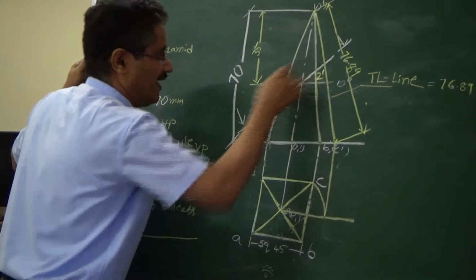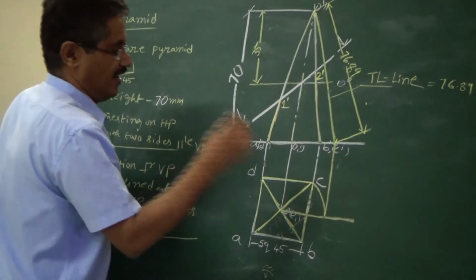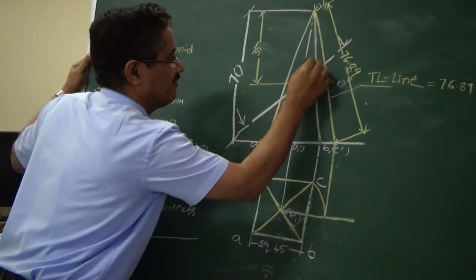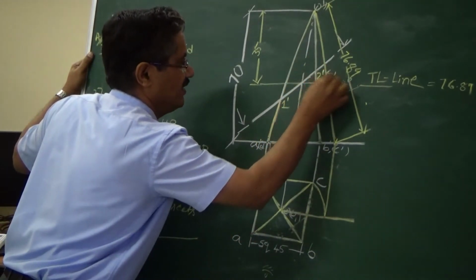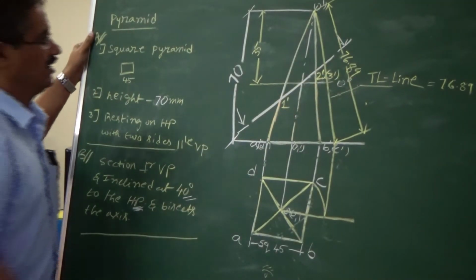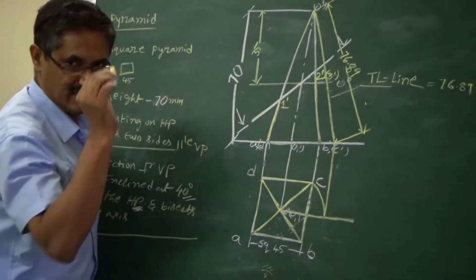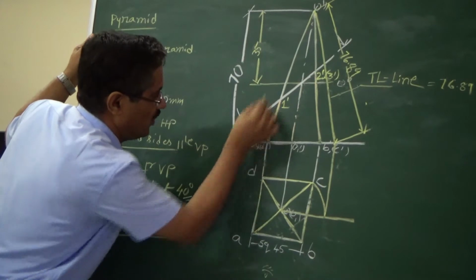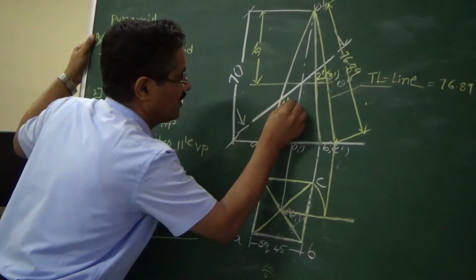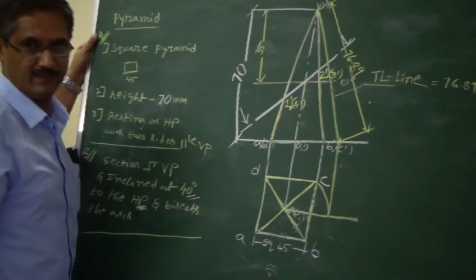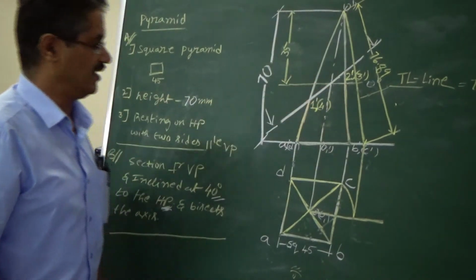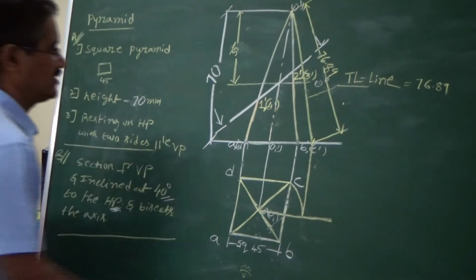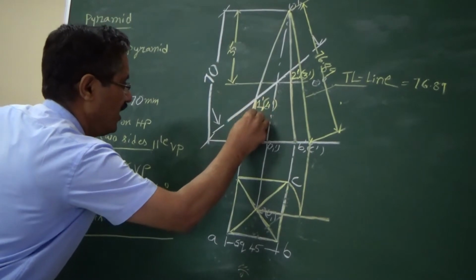Now again, while returning back, you have to number the dotted lines, that is the invisible lines. OC is invisible here. So for that we will give 3 dash in bracket. So this is very, very important. So you move down now, axis should not be numbered. Move down further, there is one more line here, OA and OD. For that I am giving 4 dash in the bracket.